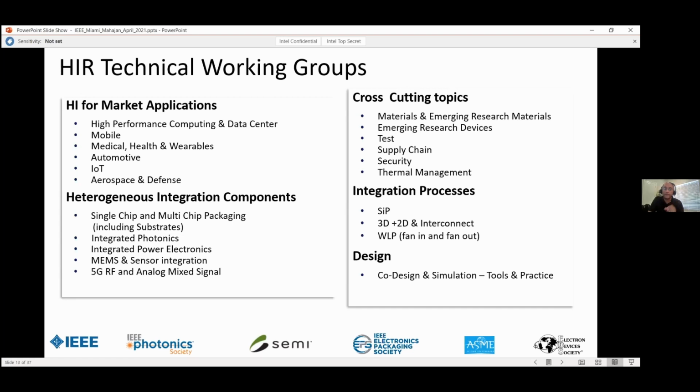We look at how to integrate these components from the perspective of a single chip, and from the perspective of multiple chips. We look at what it takes to deliver data using electronics or photonics or wireless. We look at how to integrate power delivery in all of this, and integrated power electronics. There are a number of sensors that are included in typical devices, including MEMS and RF. All of these sensors are made part of this. Additionally, when you have wireless connectivity and increasing data bandwidth as a function of generations, you have to focus both on how you communicate and how you package to ensure analog works.